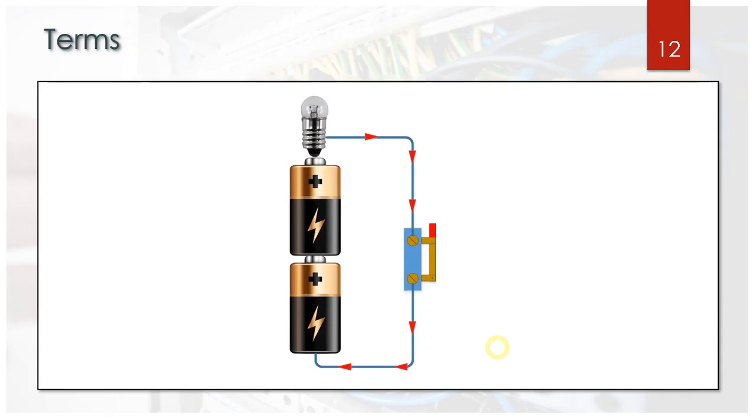Okay, so here now we have closed the switch. If you notice, this screw terminal is connected to this screw terminal. This color is to depict that this is copper, and so those are copper metal components touching each other. And now that that is closed, we have electrical current. Since we're studying conventional current in this course, we are going to come out of the positive through the light bulb, and once we've flowed through the light bulb, we're going to come through this wire through our switch and then down to the negative of our battery.